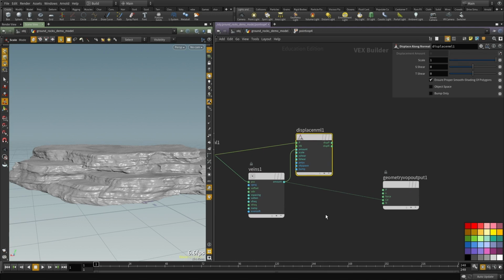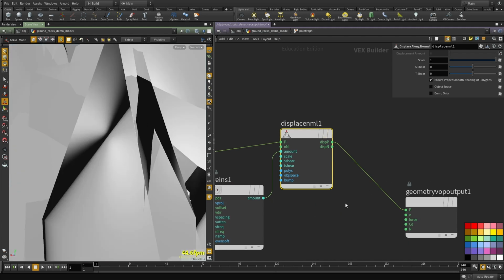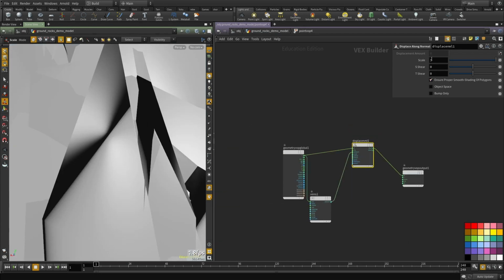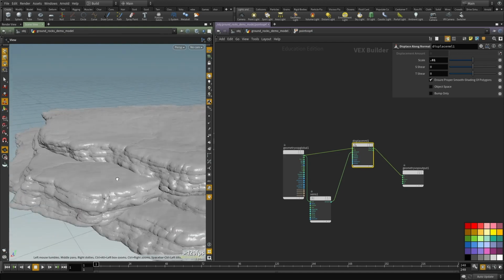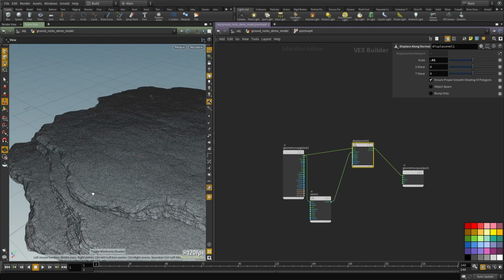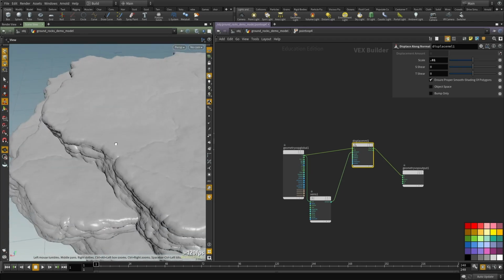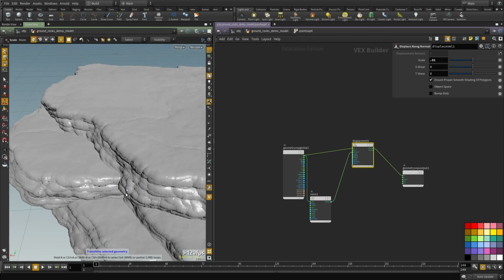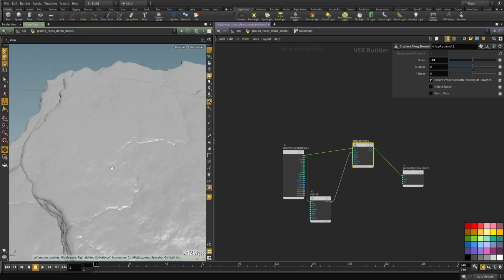That's how it works. So I'm going to connect the amount, the p, and then let's connect the position again. And now it's too high, so let's lower the scale, 0.01. Okay, cool. So see, we're getting some very interesting effects. Now this stuff is getting disturbed a lot, and that's because of the amount of details we had, the amount of geometry, and we don't want normals here. We don't want to change anything here, so we're going to create a mask for that.